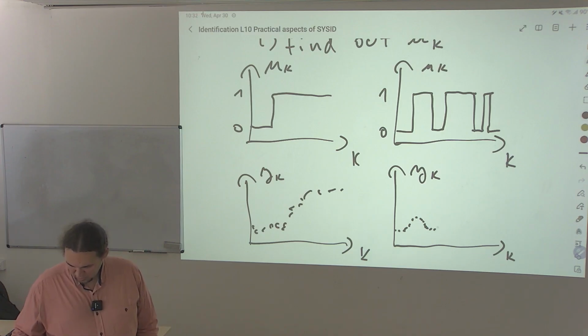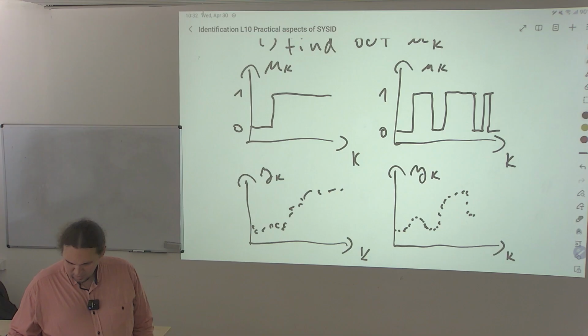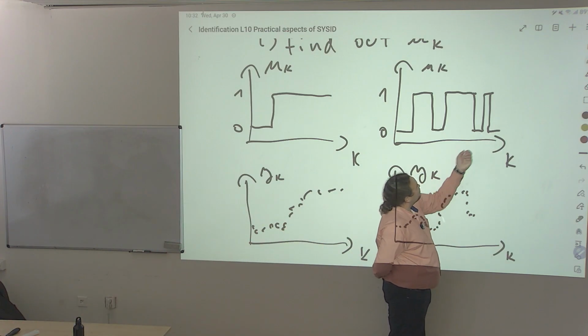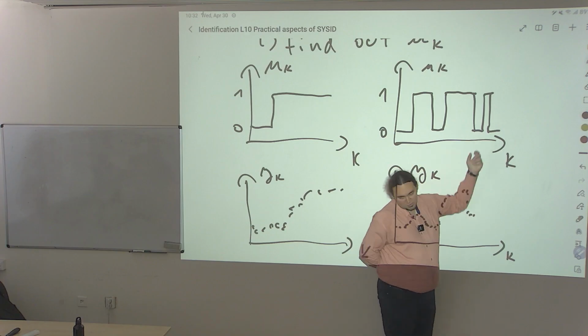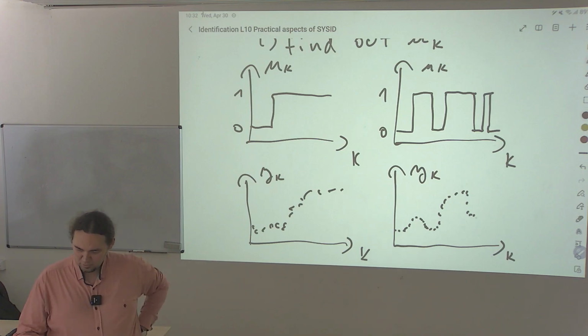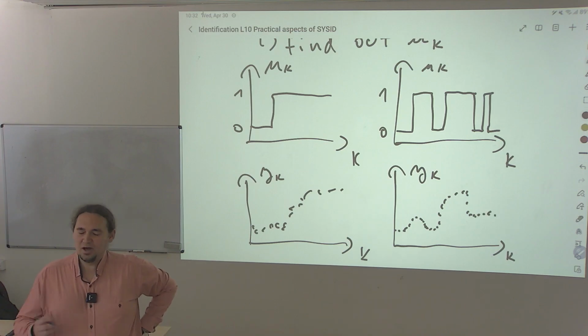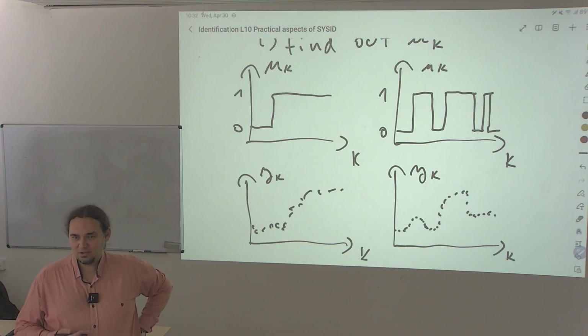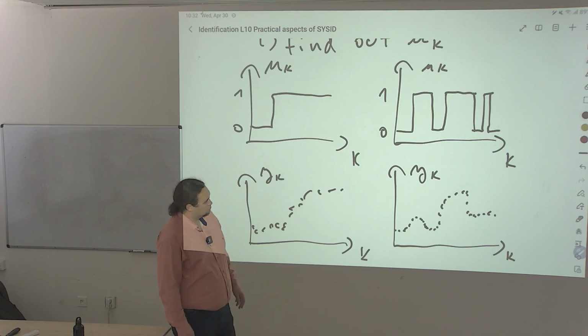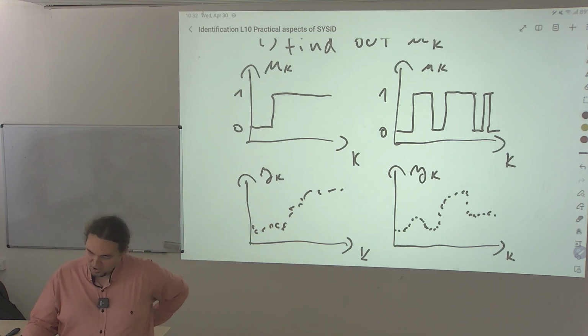The other one, maybe we already get lucky, and we get to the step response. And what would this short, almost impulse type of input tell us? Well, if there is some slow pole, the output would not even react to it, right? Because it doesn't have enough time to see the rise time of the response.